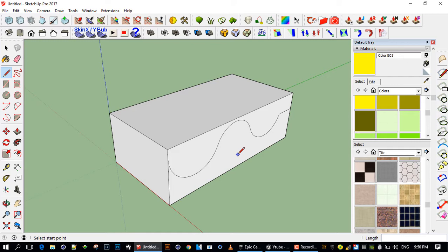It's basically a paint bucket tool on steroids, created by a developer who develops a whole suite of different extensions. The one I'm using is called ThruPaint. It's literally a substitute for the paint bucket in SketchUp. And this tool that I'm hovering over now, Joint Push Pull, is also a Fredo tool, which does what Push Pull does, but so much more.